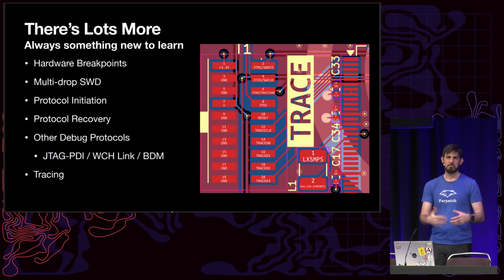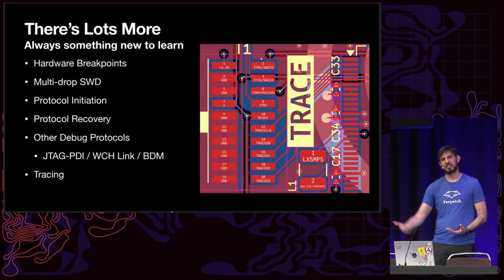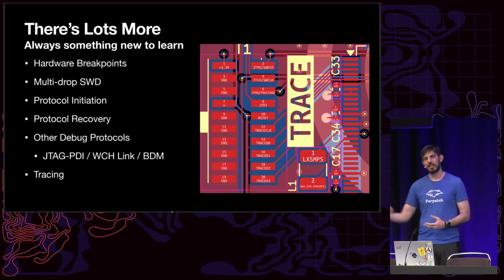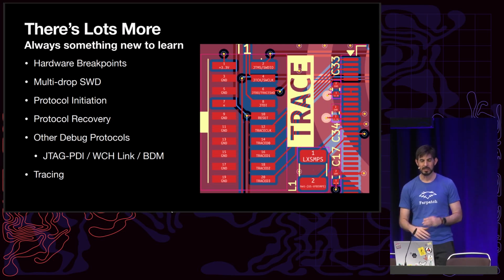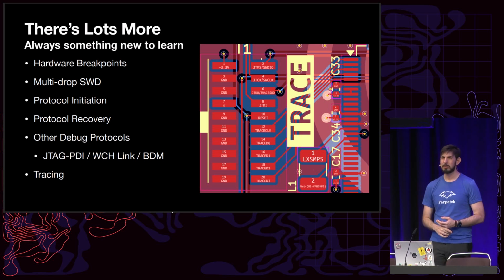If you're working on your own operating system or whatever, you're going to be doing things like changing the PLL, and maybe you mess up and now it's in a locked state. So you're going to have to recover that target and get back into a known working state. That's a very complicated series of things because, of course, if you're a hardware person, you have that nice state machine with 16 states, but as we all know from software people, things tend to get into very weird states, and getting them out can sometimes be a challenge.